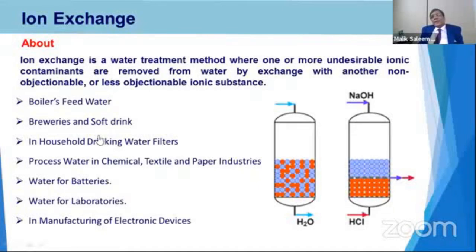After desalination or an RO, we can have ion exchange polishers, maybe cation and anion, or the mixed bed polisher, or the EDI electrodialysis systems. And basically, what the ion exchange process does is that we have a vessel filled with resins. As you know, we have cations and anions in the water. In the first vessel, we put the cation resins.